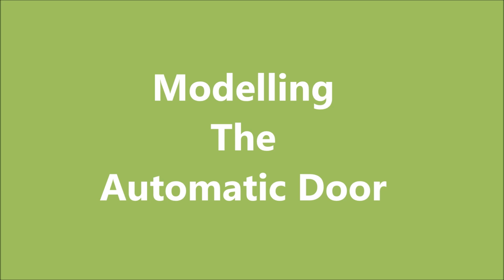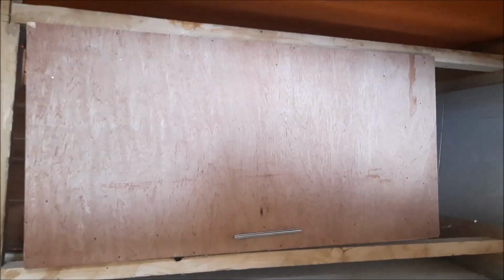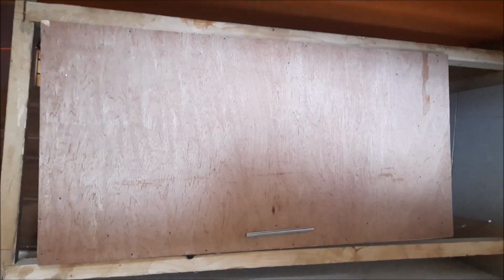Now, let us model the door. We needed a door that would be locked when there was no verification, and we also needed the door to open after successful biometric verification. We modeled such a door using this wooden framework. And on the door, we attached the solenoid lock. We will connect it to the design and energize or de-energize it using a transistor common emitter follower.